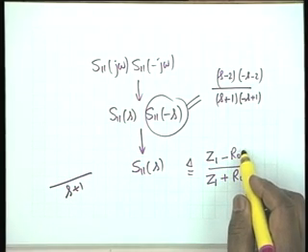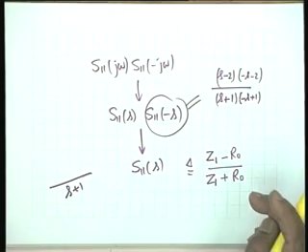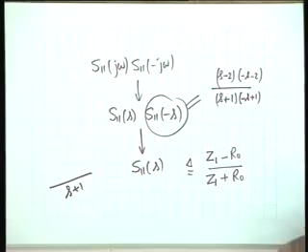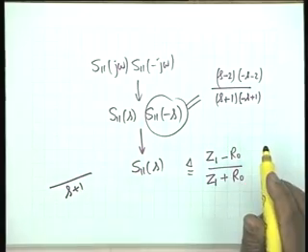The zeros in the right half plane shall go to S11 of minus S. Here, for example, S11 of S is absolutely clear. Okay. Here, for example, for S11 of S, you will have to choose only this factor in the denominator, S plus 1. As far as the numerator is concerned, you have a choice. Numerator is a difference between two impedances, and a difference between two impedances can have zeros anywhere in the S plane. It is not restricted. Okay.